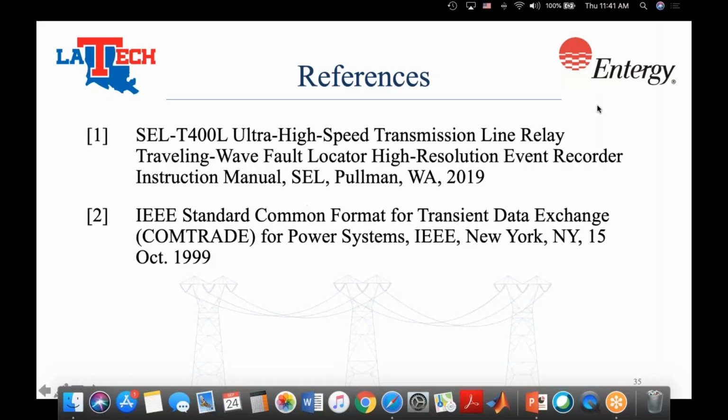Thank you. And for their frequency characteristics, how did you get those? So we are working with the manufacturers to do some tests for us. The relay manufacturers provide some data, and we're also looking at some literature to develop a high frequency model of the PTs and CTs. Again, we're definitely working on it, but it's not a fully completed model yet, and we're also working on a paper. So we hope to get that sorted out within the next couple of months. But basically, we're relying on the manufacturers to do some tests to provide us that data.